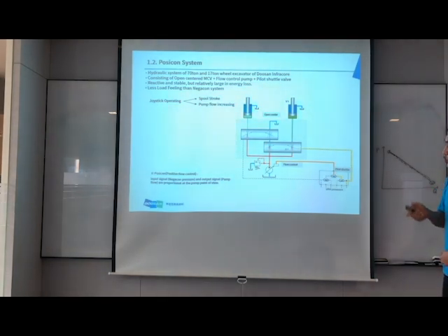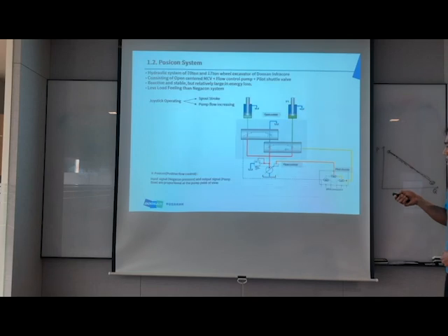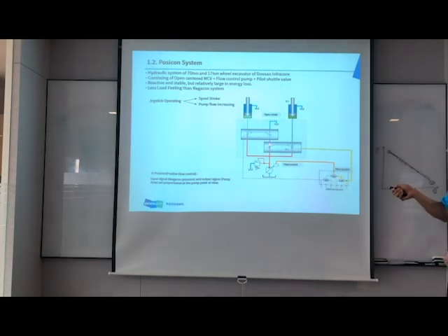When the operator moves the joystick, the spool is shifting. Actually, this line is from the joystick. So when the spool shifts, this line is also clogging. And also, this line is slightly open. So the discharge oil goes to the cylinder. Finally, the cylinder is moving.